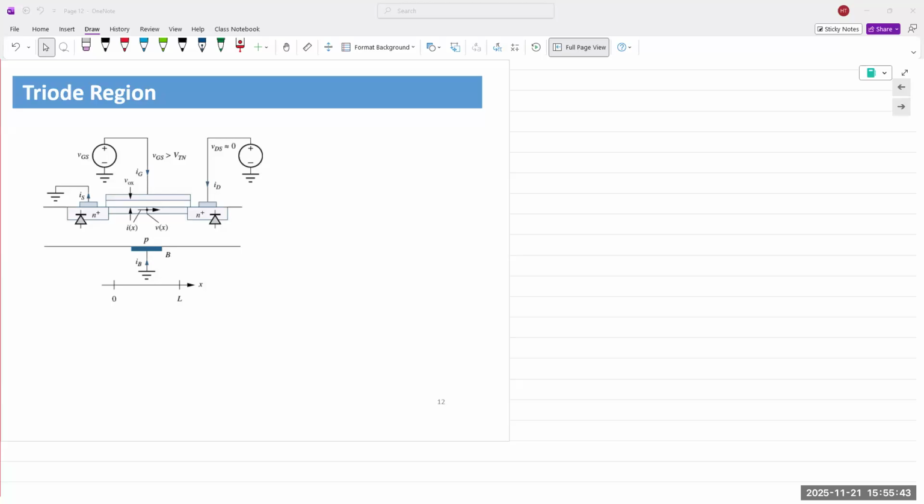You have current flowing between emitter and collector, and you have a base current that is controlling the flow of this current. Similar to this, we have current flowing between the drain and the source of a MOSFET, and you have the gate voltage that is controlling. The big difference is in a BJT, there is actual current flowing into the terminal. For a MOSFET, there is no actual current flowing in. So it's in a standby state, no power loss. Very negligible. That's the biggest advantage.